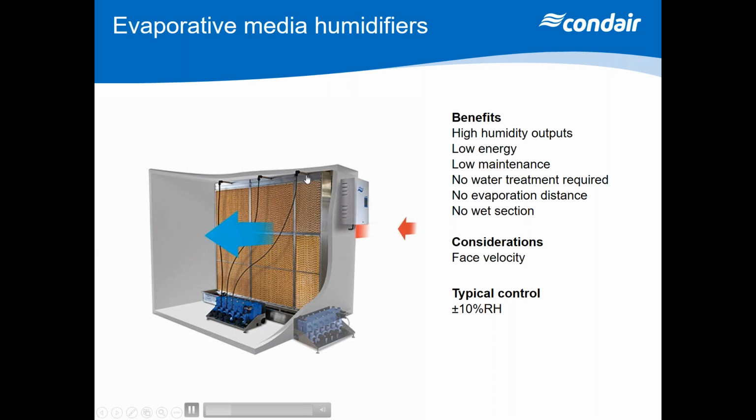Water then cascades and soaks this glass fiber material, and a proportion of that water will be evaporated off, giving you your subsequent evaporative cooling, i.e. that we are evaporating water into the air, increasing relative humidity, increasing moisture content, but decreasing dry bulb temperature.